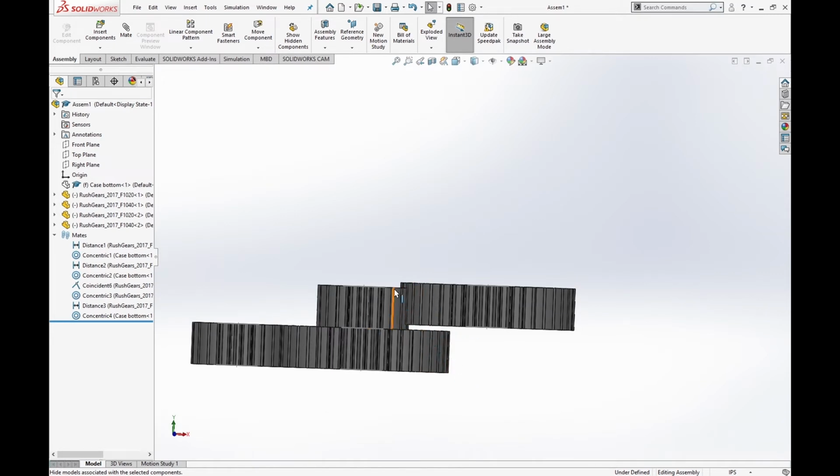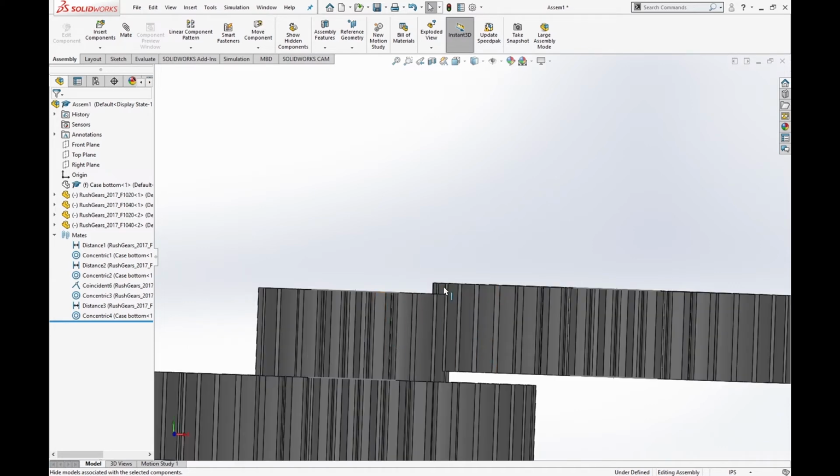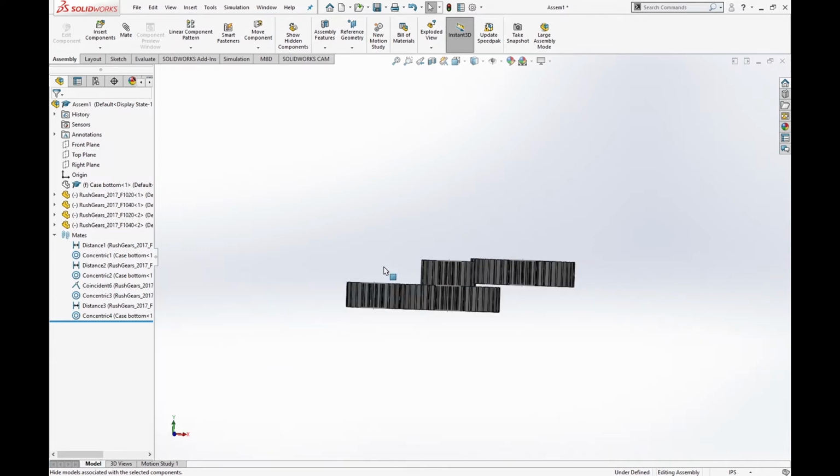This gear is taller than this gear. I would bring this gear down to this size, just because there's really no point of having this gear. It's not in bending, or it's not being stressed when there's nothing meshed to it. So you want to make sure that this gear is at the max at the top of this gear and nothing above it. And that's what you do in your gear analysis.